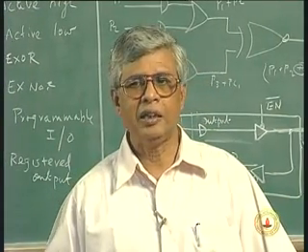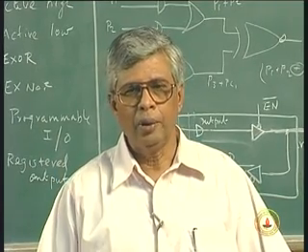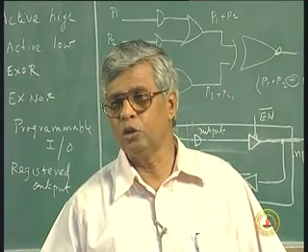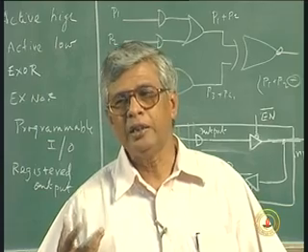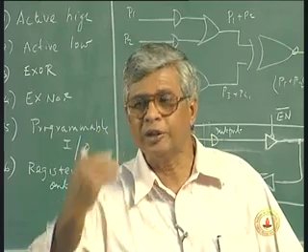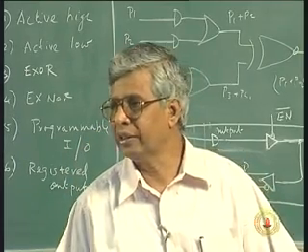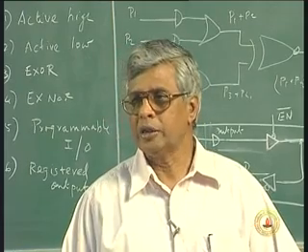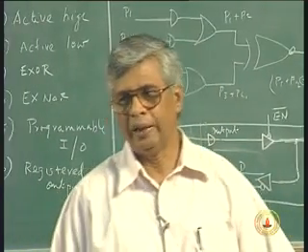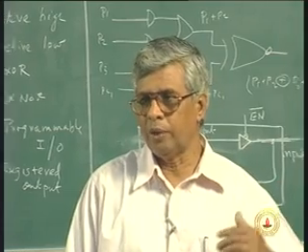But what we have seen in the class till now are very small devices. So ROM can be of any size, but larger size means larger memory space and power, and we do not want to use them. As I said, a large ROM is inefficient for a design, because a large ROM means a large number of inputs and all the minterms are generated. When all the minterms are generated, only few of them are used, it is inefficient hardware utilization. So, leave that out. ROM based design, one is required, they do it, lookup table approach, but generally only when the size is small, they use ROM. That leaves two other alternatives, programmable logic array and programmable array logic.